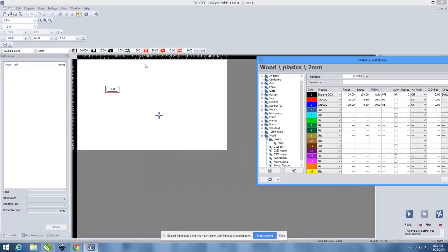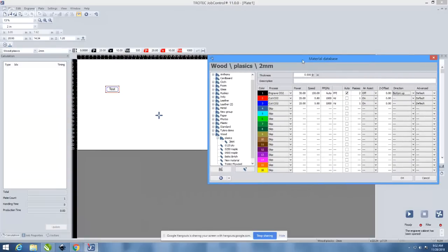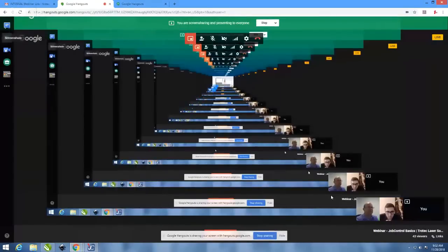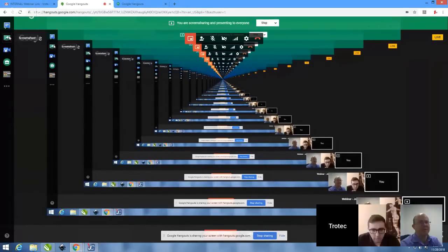What it does is, when you're engraving from the bottom up, the exhaust is at the back of the machine. And it allows the exhaust to pull the smoke and debris across an area that hasn't been engraved yet. So if you do the other way, top down, it's actually pulling it across stuff that's already been engraved. It might be a little warm, might be a little bit sticky. So you end up actually getting some of that smoke sticking to your engraved area, which is what we don't want.